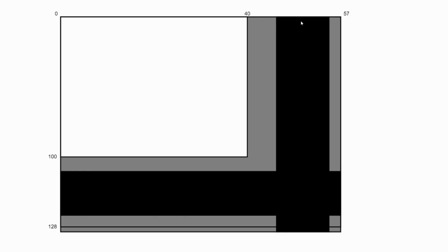But basically, if we move these blanking regions about, we're also moving the sync pulse about, and so it has the effect of making the screen appear to shift left or right, or if we change this up or down. So there's a whole load of things that we can control by fiddling with these registers. The real fun of this project is going to be to figure out exactly when can we change these registers.